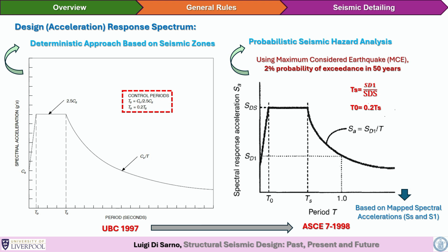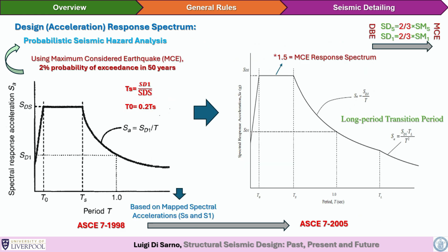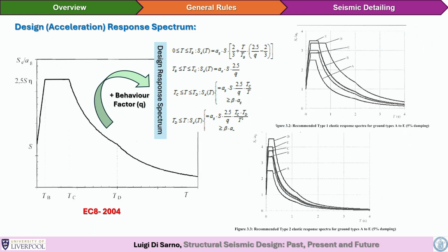So please be aware that there is a close match between the reliability implemented in the input, in this case in terms of earthquake, and the seismic detail as prescribed in code of practice. This is something that engineers should also check to be consistent with their design. And again, some changes to move forward up to ASCE 7-05, where there are also some indications for the long period and short period type of approach. But this is part of what is currently implemented in code of practice. So nothing new, simply a comparison and an evolution in terms of spectral shape based on more data.